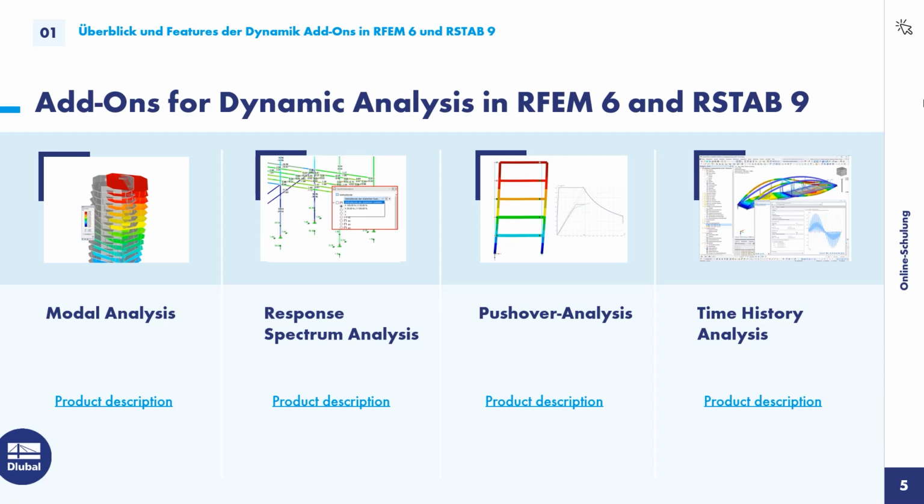There are different shapes, for example, a rectangular shape, a triangular shape, and also a modal shape. So we need the modal distribution to create that loading. The pushover analysis itself is mainly used for retrofitting structures.